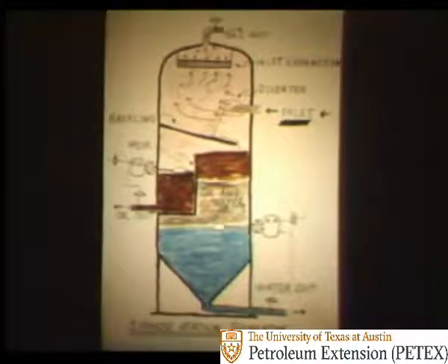The water which settles out of the oil in the first compartment is controlled by an interface float, which is the level where the oil float contacts the water. The interface float and controller operates the water dump valve to prevent oil from leaving at this outlet.